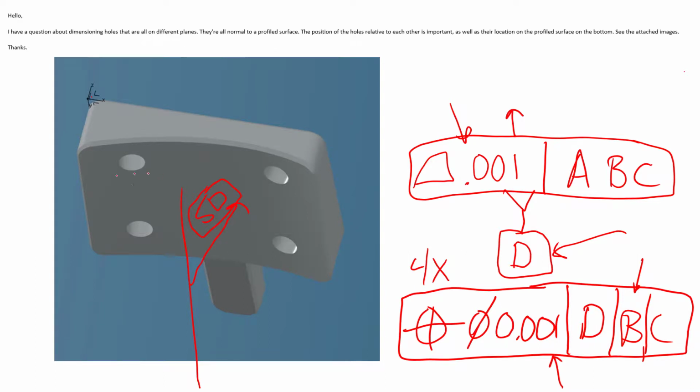And we'd also need to make sure that everyone understands, is the axis centered to this part? Like in that direction? Or does the axis over there? Is the curve kind of warped? So we'd need to basically make that in basic dimensions, locate how far over is that center line. You can't just assume center.